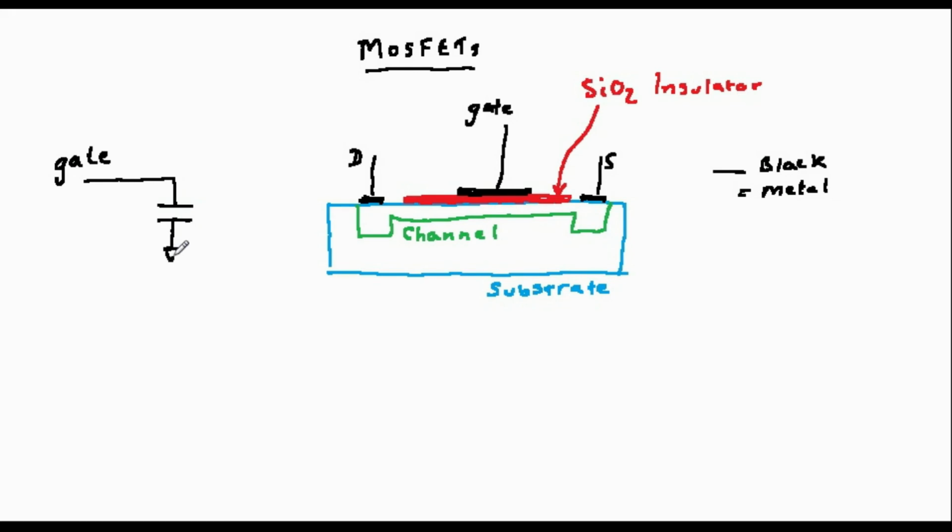It makes the device sensitive to static electricity, and a static discharge can blow a hole in the sensitive insulating silicon dioxide layer and destroy the device. Precautions against this include wearing an earthed anti-static wristband, using an earthed soldering iron, and storing and assembling MOSFET circuits in and on a special anti-static conducting material. MOSFETs make excellent low-loss switches for power and digital electronics, and also amplifier input sections when very high impedances are required.